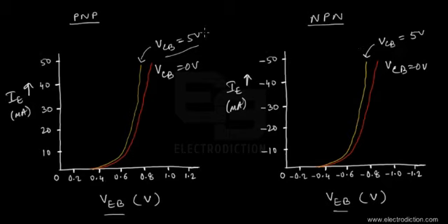In this case it'll be a -1. I'm just going to write it down clearly. All right, that's better. So in the case of a PNP type of BJT, the reverse bias collector base voltage is of course taken negative with respect to ground, while in the case of the NPN type of BJT, the reverse bias collector base voltage is taken positive with respect to ground, depending upon the voltage source terminals being connected and their polarities, of course.